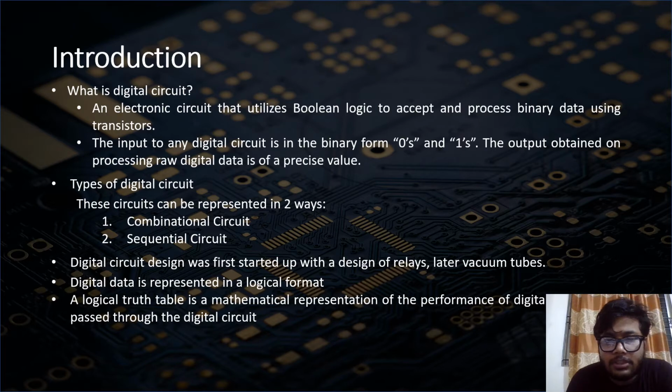A sequential circuit is a combinational circuit with some of the outputs fed back as inputs. This circuit performs a sequence of operations in zeros and ones format. Logic 0 represents that the signal is low or GND, and logic 1 represents that the signal is high or connected to the supply.